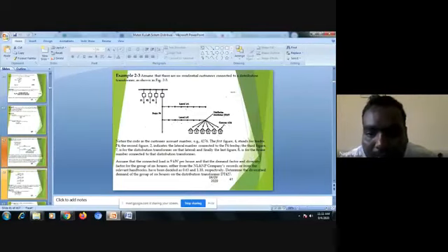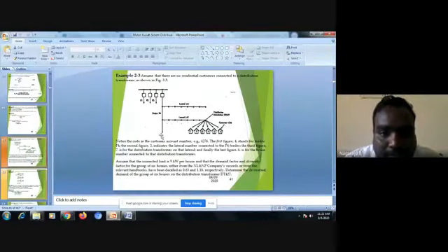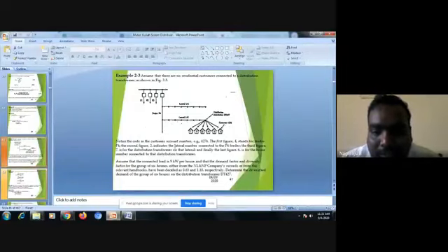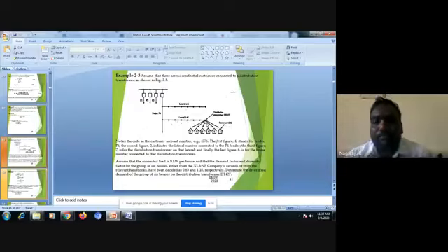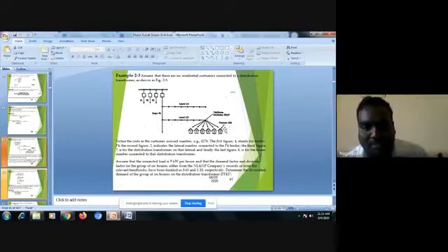The figure 4 stands for the feeder F4. Feeder F4, I have the tapping. The next figure indicates the lateral numbers connected to F4. 1, 2 laterals. These two are the laterals. Finally, the last figure 6 is the house number connected to the distribution transformer, from this distribution transformer here.